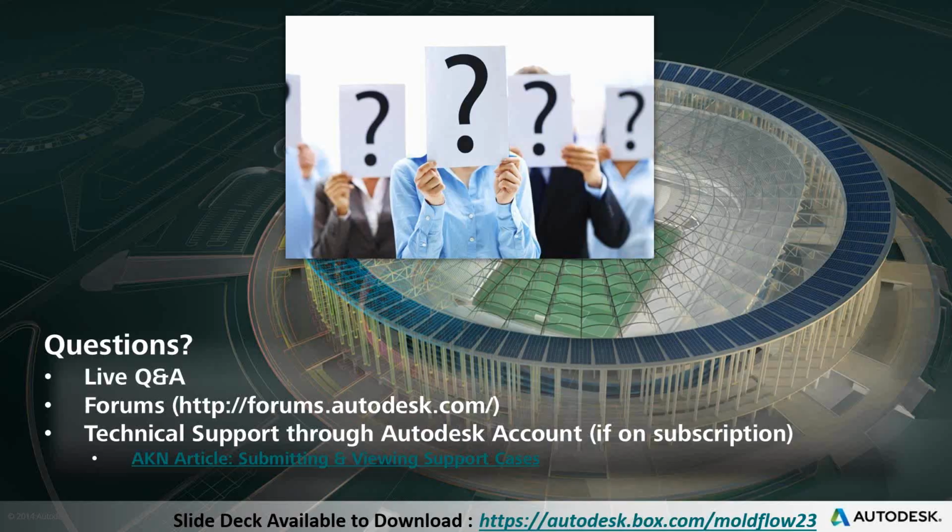Yeah, I'd say that's definitely the first place that we would start as if say we got a support case in where someone was coming to us saying their parts had way too much deflection or warpage in there. We'd almost start working backwards and make sure our process settings match from the molded part to the simulation, as well as just the general setup of it.